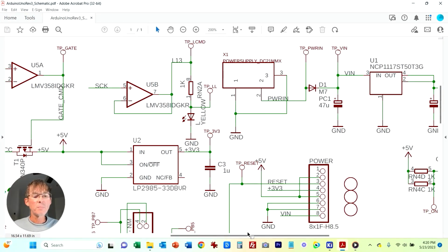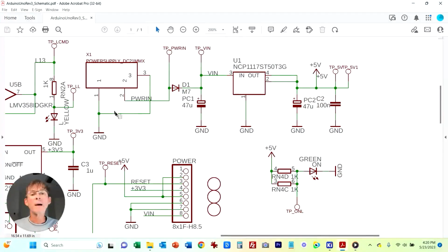So now it's basically just the power connector. They're calling it power in. It's going to go through a diode here. This is just to make sure that you can't have power going the other direction. So you are going to lose a little bit of power here, a diode drop. That's probably why... oh, well, that's 2.1 millimeter.